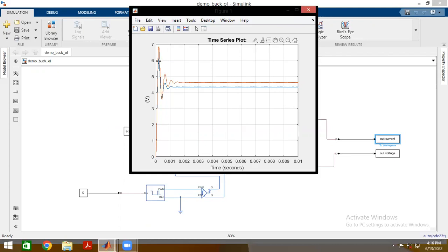And one other thing that is actually catastrophic is the overshoot here. For the heavy load, the overshoot is not as significant, but it is still high. We shoot all the way up to 5.9 volts, and we end up settling at 4.3. So that's a large overshoot. And with this one, we shoot all the way to 6.7, and we end up settling at 4.6.